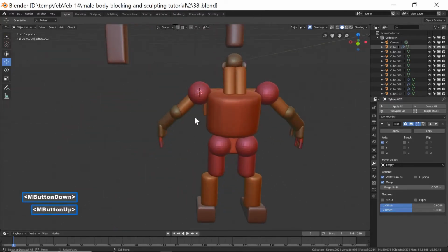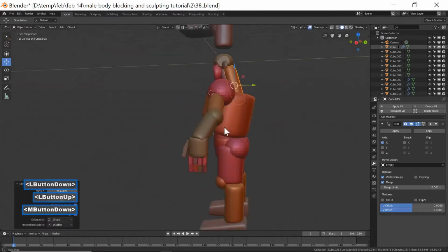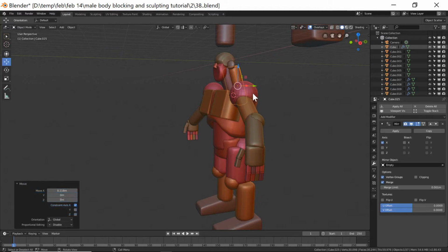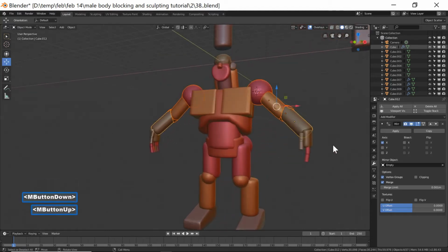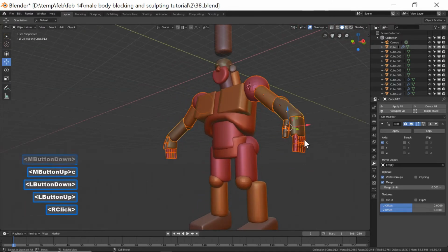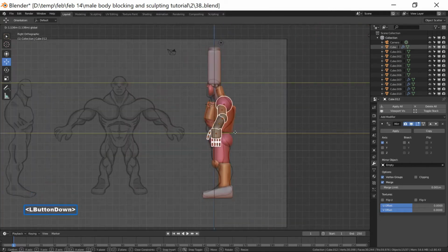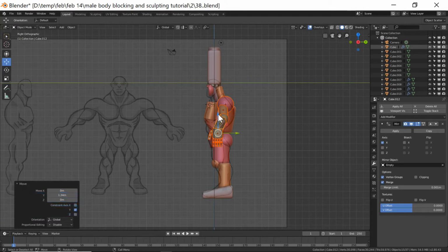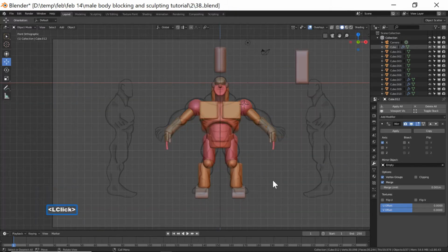I'm going to hold the middle mouse button. We don't want the shapes touching in the center. The arms, by the way. So I'm selecting all this. I'm going to press C for paint select to select here. I'm just holding the middle mouse button to rotate. Arms, I'm going to press 3 so you can see this. The arms should be back more. You don't want the arms to the front. I'll press 1. Okay, I'm going to left click to deselect.